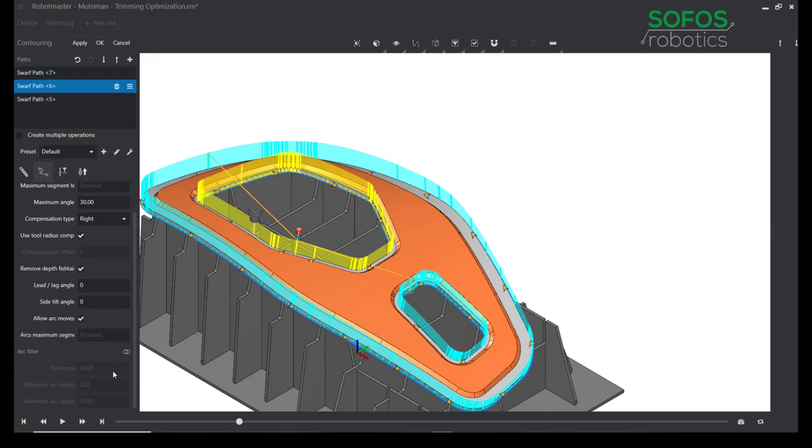We could do arc filtering if we wanted to. That might help with some. I think we're okay though. This will essentially, instead of outputting a bunch of linear moves to get around an arc, fit an arc to that curve and output circular moves.